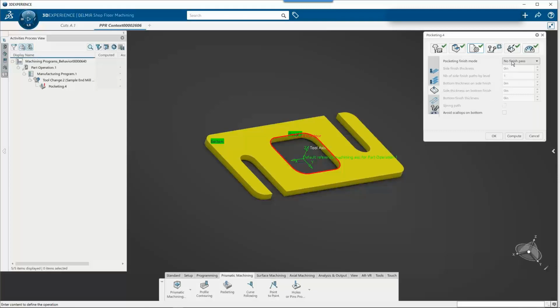If I wanted to do finishing, I can do roughing and finishing. We combine a lot of our operations. So instead of having a roughing operation and a finishing operation, we can combine those together in one step if we want. I can copy and paste, rename this to roughing and just do roughing, then copy and paste it and just turn on finishing. We have full control to do that. But in a lot of instances, I want to rough this and then I want to finish it. If it's not super high tolerance, maybe I just do it all in one step, or with one cutter. The choice is yours.